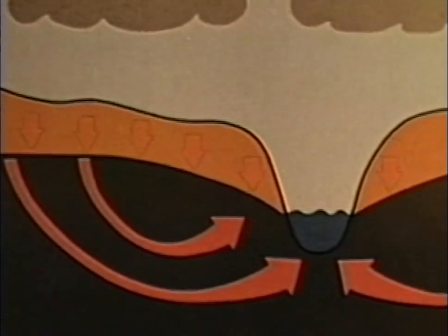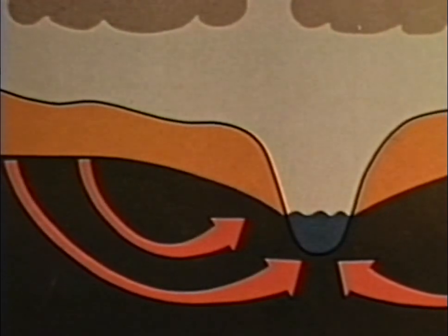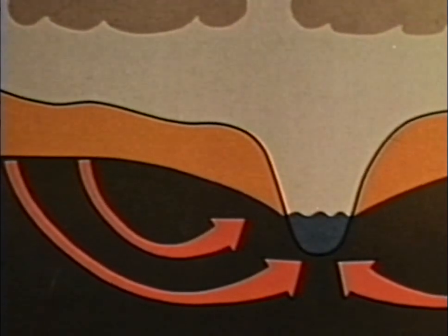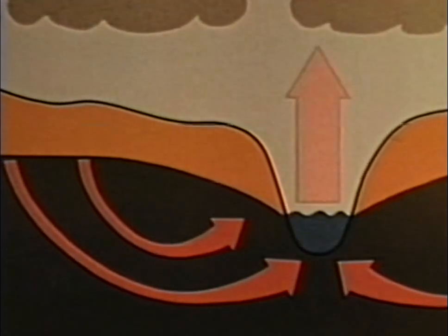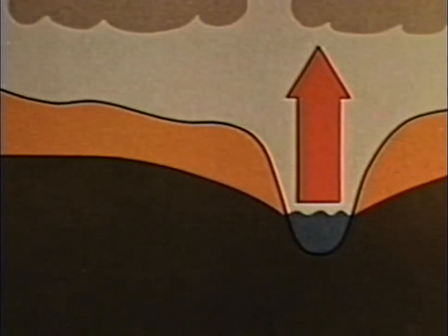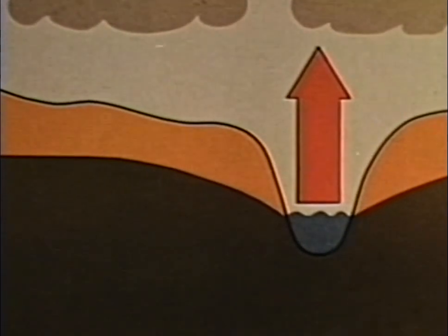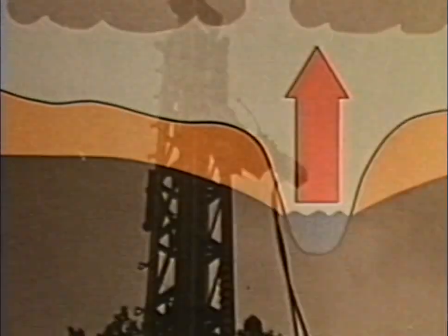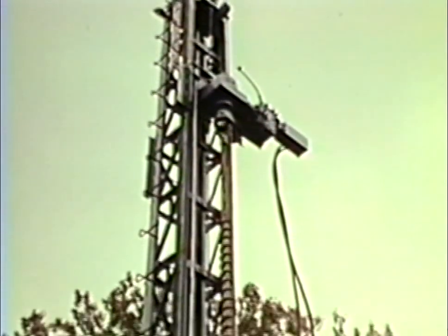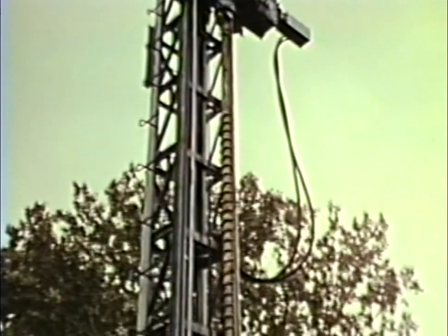Below the water table in the groundwater zone, water continually moves along flow paths from zones of high to lower fluid energy, some of it flowing into surface water bodies where part of it evaporates. This passage of water through the atmosphere, through rivers and lakes, and through the ground is known as the hydrologic cycle.